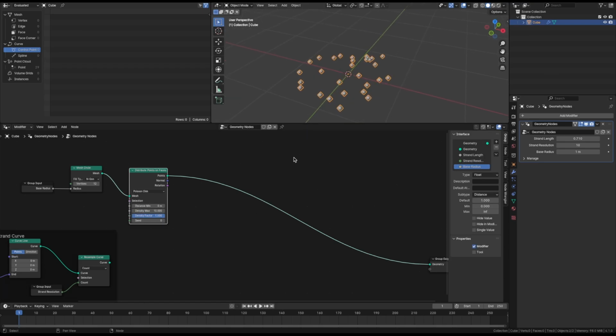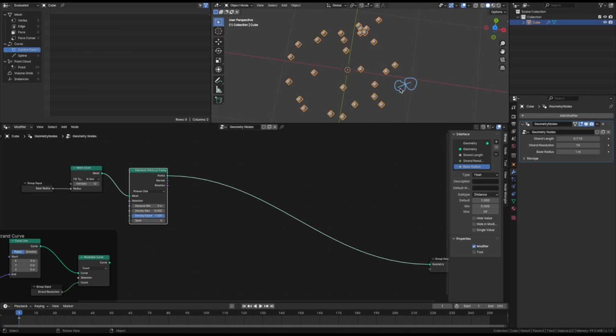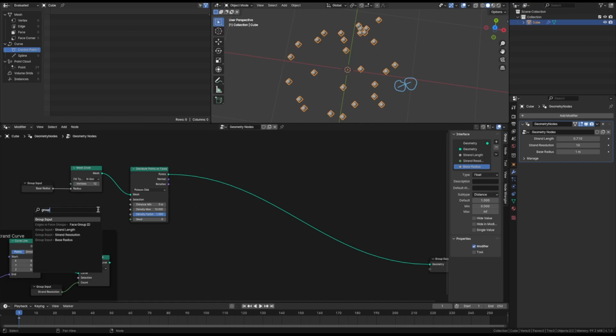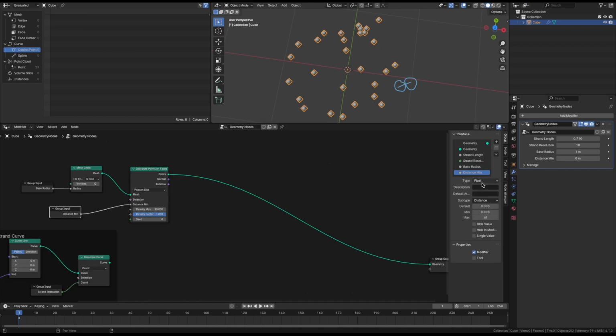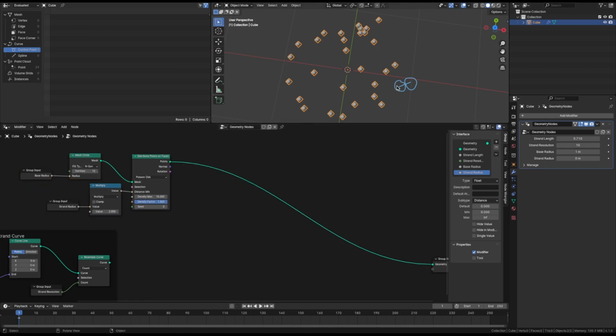Those splines will eventually be cylinders, essentially, and we want these points to not get so close that the cylinders intersect. We want them to be separate enough so that they're side by side. That's the distance of 2 radii. So to specify that, we'll say minimum distance should be whatever the input of this radius is. We'll call it the strand radius and bring in a math node and say times 2. And that will prevent them from being so close that they will actually intersect.